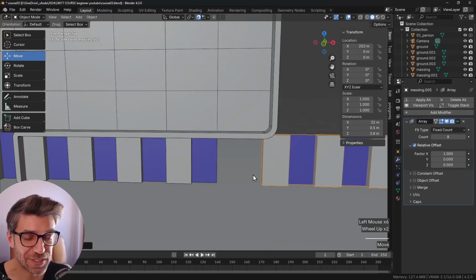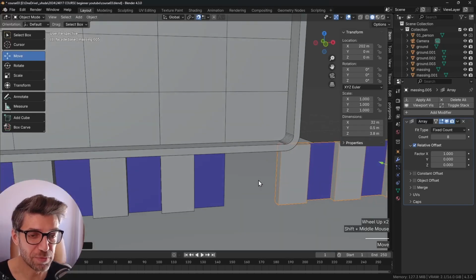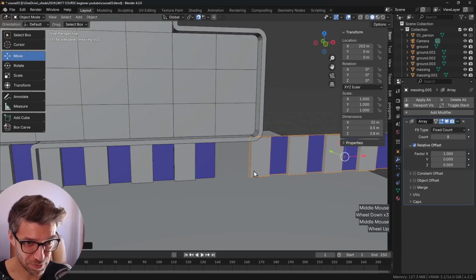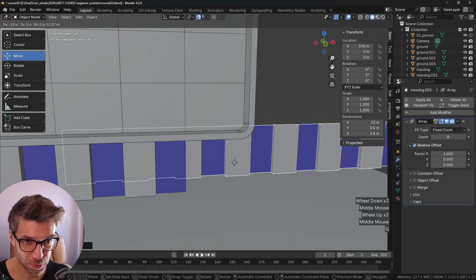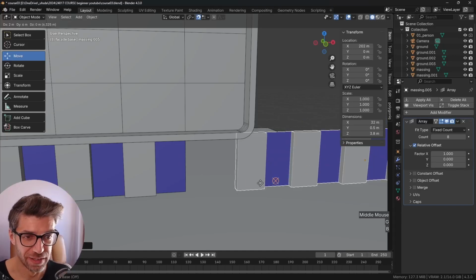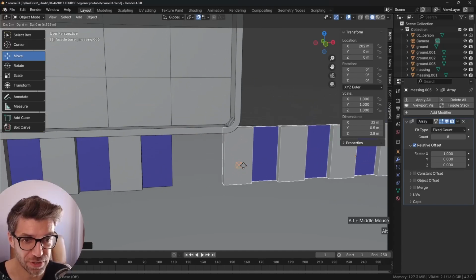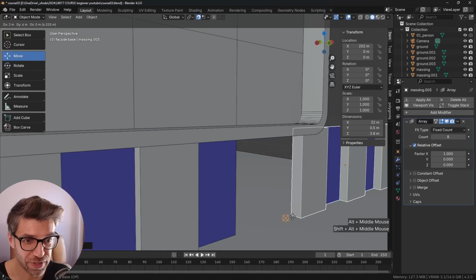Okay, so this is an excellent reason to show you one of Blender's new features, which is snapping with a base point. Believe it, it took a while for that feature to get implemented. So how does that work? So G to move, press B. That's the thing that it's a little bit still tricky because it depends on a lot of hotkeys. So G, then B to select the base point. And we can also move around in the 3D viewport by holding Alt or Shift Alt to rotate.